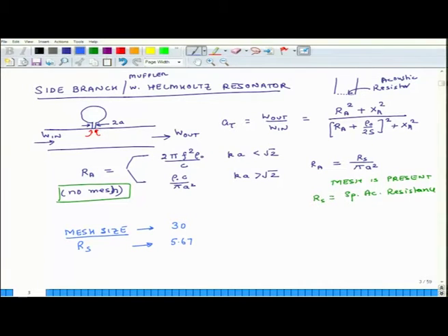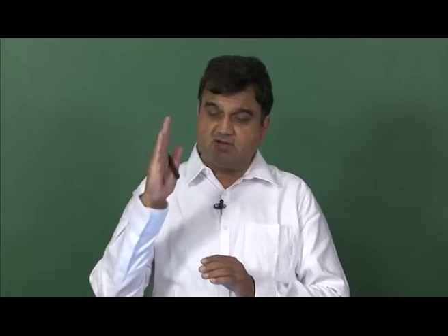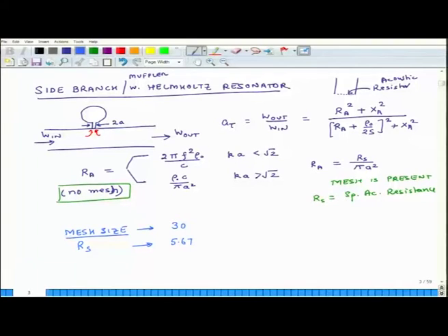The number 30 means that in 1 square inch of area, there are 30 by 30 wires in each direction. Okay? It is a grid of 30 by 30. So, this 30 tells us how closely packed these wires are in the mesh. So, if the mesh size is 50, that is 50 wires per inch, then this number is 5.88. If this number becomes 65, then this is 6.4.